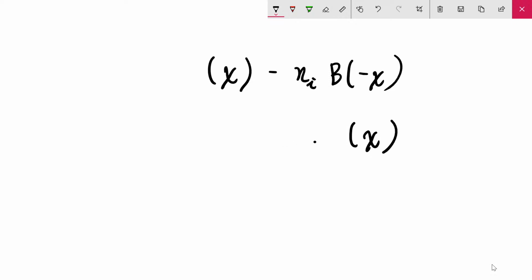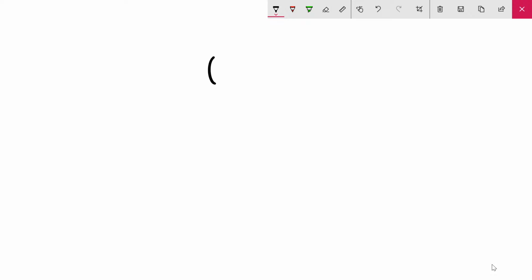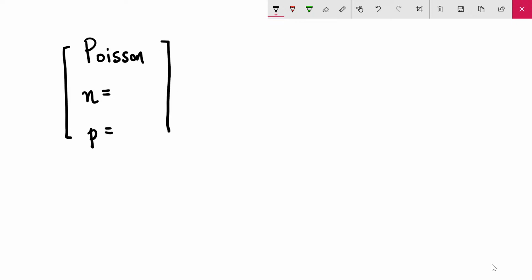So previously you did your homework for a system solving the Poisson equation and an expression for electrons and an expression for holes. Yes, that is strictly valid at the equilibrium case. But now you have the Scharfetter-Gummel scheme. So obviously the next goal is to first solve this system.